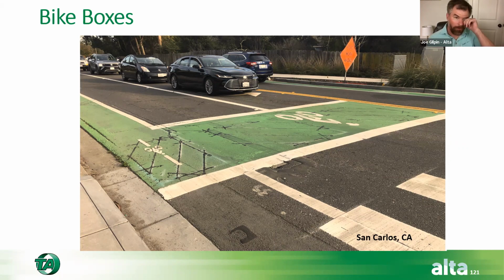But one thing, if you have a multi-lane approach like this one, some things that you have to worry about, particularly if you're using it for left turns, which I've already mentioned, maybe to have a second think about whether there's another way to do that, is that if a bicyclist is positioning to get over here and they're sideways and the light changes, that's also kind of uncomfortable.